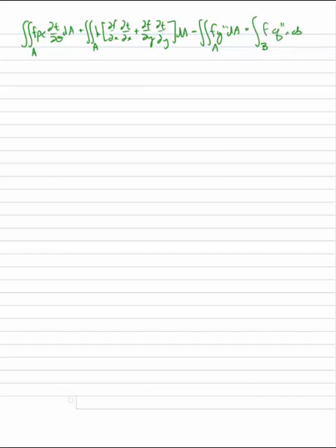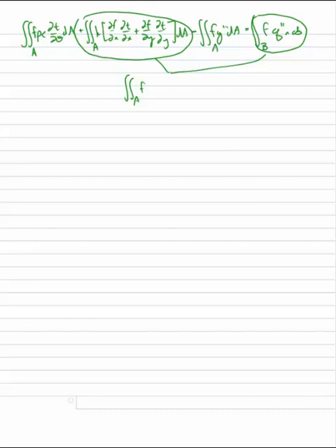And what made the weak form different from the strong form was that this term and this term used to be something maybe a little more familiar, which was the integral over the area of f times d/dx of minus k dT/dx plus d/dy of minus k dT/dy, like that.